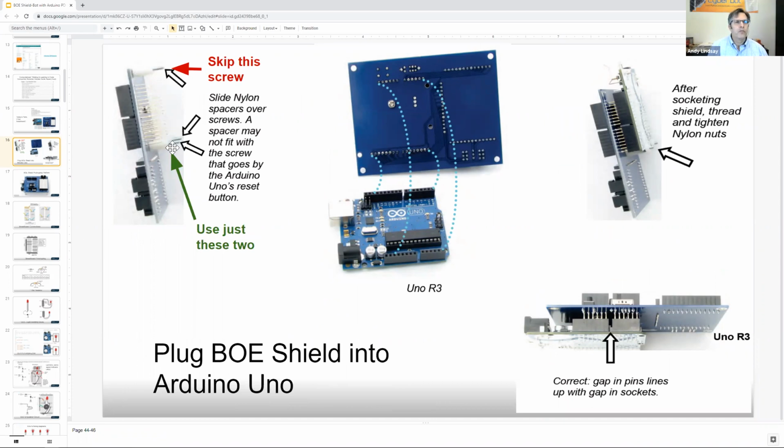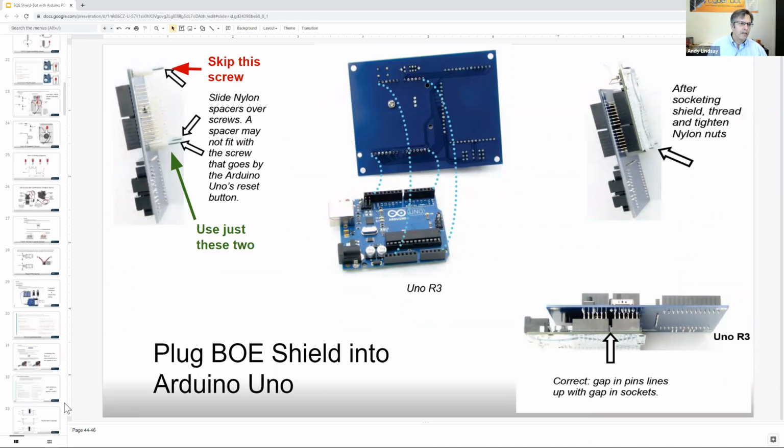there were some screws and spacers. The thing that I'm always concerned about having damaged is, if you don't use these screws and spacers, it puts a lot of stress on these pins that hold the Arduino underneath the shield. So my main concern is making sure to get these screws holding the Arduino in place, so that when you unplug and plug the serial cable, the USB cable, pardon me, there's not stress placed on these pins that are sticking out. So I think that's an important consideration.